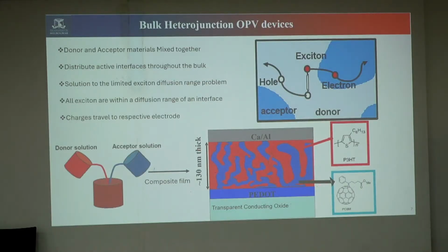Like I said in the morning, instead of making one layer and another n-type layer, we mix both together so that the donor and acceptor phases are very close to each other. Then we coat it. Compared to the previous one, here the donor and acceptor phases are very close nearby. So here one heterojunction, here another junction, everything, the PN junctions, will form closely within the layer. The many junctions are why it's called bulk heterojunction.